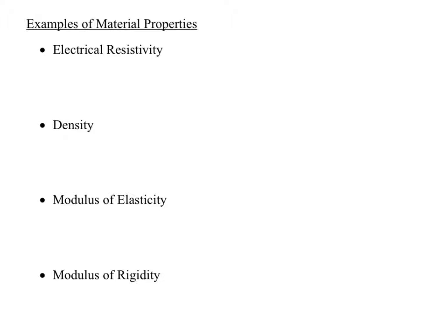All right, the next part, the modulus of elasticity and rigidity. The modulus of elasticity is also known as Young's modulus. It's a scientist's last name; they usually name it after the person. The modulus is like the equivalent of the K value. Anybody remember from physics last year with springs? What did the K value represent for a spring? Yeah, the strength of the spring, the rigidity, the spring constant. So if it was a larger K value, it took a lot more force to stretch the spring.